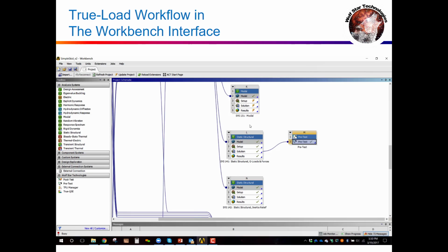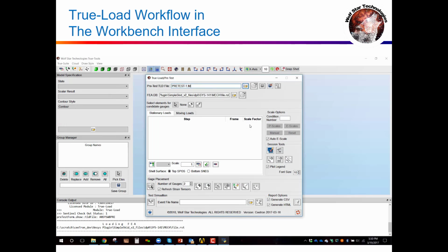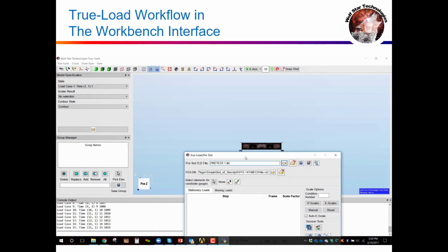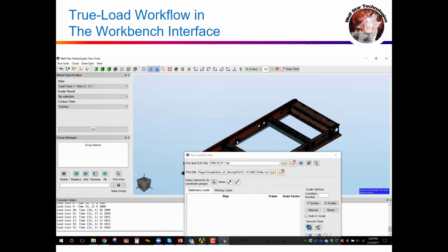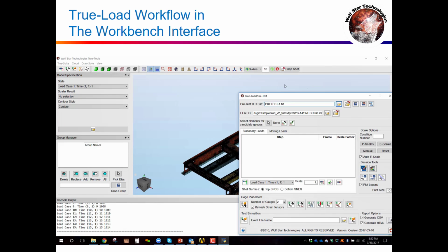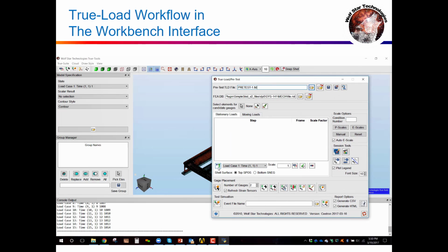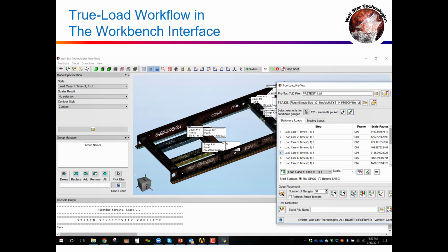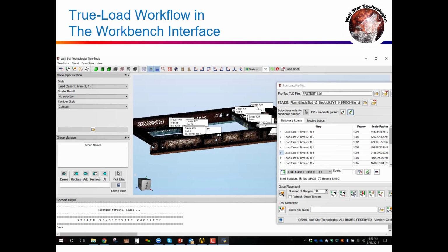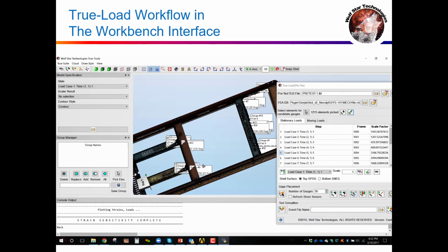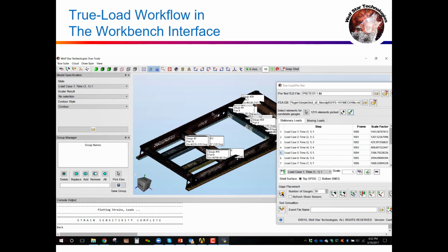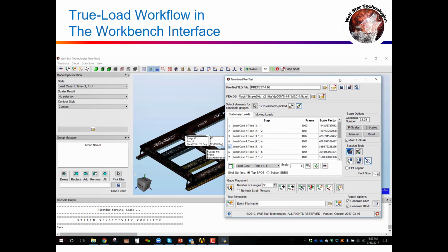And so here's the pre-test module. We just load in all the unit load cases once it comes up. Here's an isometric view so you can see what we've got. And load in the unit load cases. Then, through a series of steps, we've selected elements and told TrueLoad to lay 30 strain gauges here to be sensitive to our 15 unit load cases. Okay, so it's a very easy, very straightforward task to lay those gauges and get done.